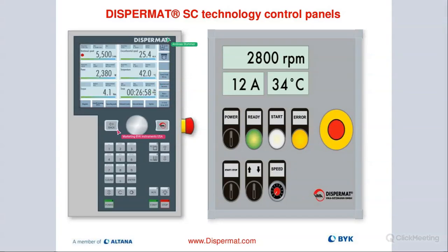Then the two windows on the top right corner, you can see H1, H2, which is the safety device for our container reference points, and then the container clamping safety system right below. They would light up green when they are operational or the machine is in safe mode. If one of those two is not in a safe state, it would appear red and you wouldn't be able to turn on the machine. We offer that for the lab, pilot, as well as manufacturing size machines.